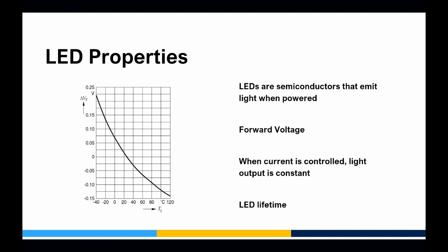But again, over time, all LEDs will get darker and darker. We'll once again increase our intensity up to 100%, and then once again over time it'll darken. And then once we're at 100% and our image is too dark, it's time to replace the light. But by starting at 80% and giving ourselves the ability to increase the intensity of the light by 20%, we gave ourselves a few more years with that light before we needed to replace it. So we're not necessarily changing the LED lifetime, but we are changing how long we go in between replacing lights. So that's just one benefit of a controller right there.